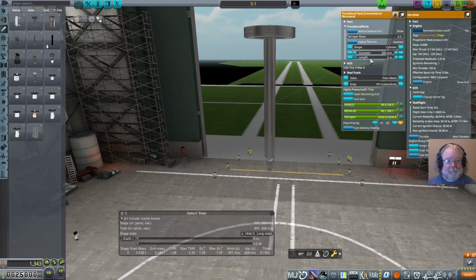So between 3 and 3.1 meters. The tutorial, we want to match the tutorial. The tutorial picked 3.1 meters because remember we want to go slightly over. Having a little bit of extra fuel is good because the engine might last longer than its rated length. And if it does, then you've got the fuel to make it available, so go for it.